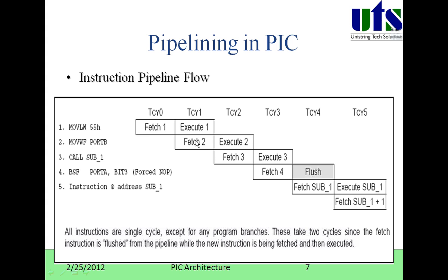That means one complete instruction is executing here. For that reason we say that RISC property instructions execute in single clock cycles. Fetch and execute together complete within Q1, Q2, Q3, Q4.